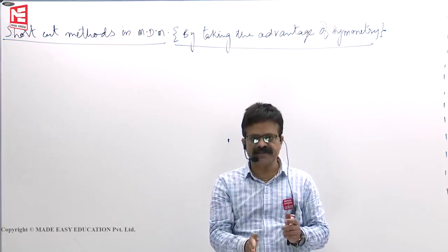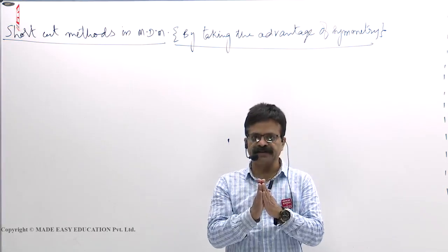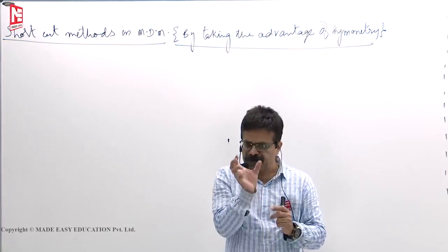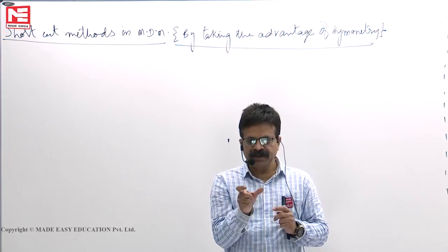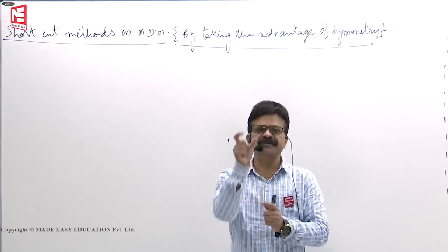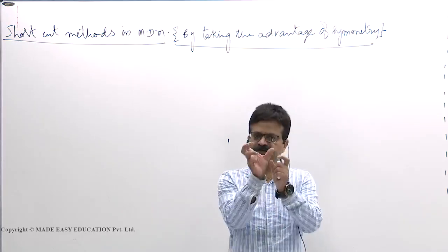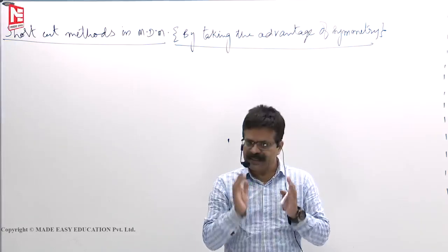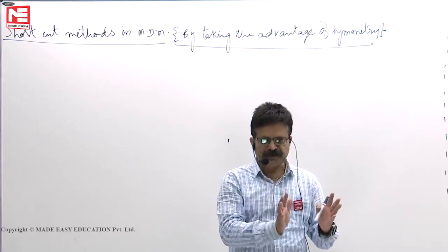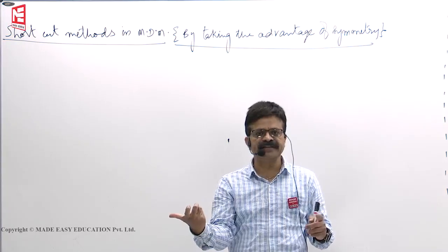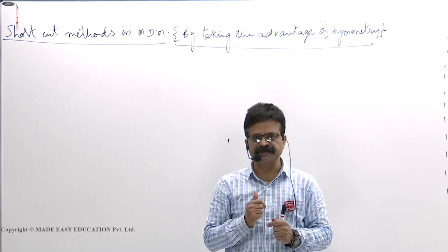If the axis of symmetry passes through the midspan, then what we do is remove that central span and replace it with another beam whose stiffness is half of the original member. Then carry out moment distribution only for half of the frame or beam. Whatever moments you get, with opposite sign you write on the other half of the beam or frame.